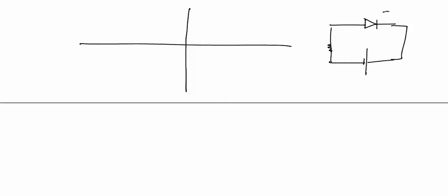Now for this reverse biased PN junction, this is the voltage across this PN junction VR. It was VD in the case of forward biased PN junction, and it is VR in the case of reverse biased PN junction. And this voltage V is applied. Due to this voltage, a small current flows through diode, which is equal to I naught called reverse saturation current. So in reverse biased PN junction, it conducts very less and a very small current flows through diode.